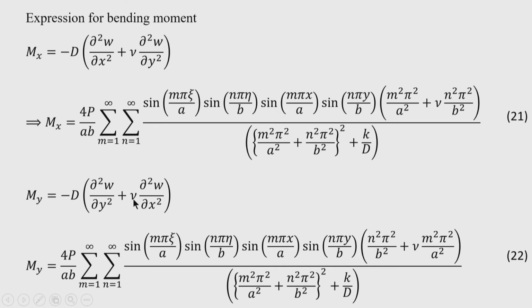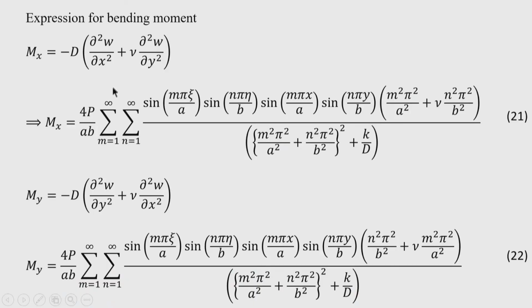So, that you should remember. If it is a steel plate, the Poisson ratio generally varies from 0.25 to 0.3 or around this, and if it is a concrete slab, then we can take Poisson ratio 0.15 to 0.2. Okay. So, my can be determined, mx, as mx is determined, my is also determined,